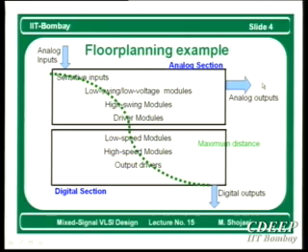And the way I put my pins exactly will be like this. It means that now these digital outputs will go to the pins which are at the bottom. Analog inputs will come from pins which are at the top. And then analog outputs will go to the output pins which are on the right. So this will give at least a preliminary provision or preliminary precaution about interaction between switching noise which is coming from the digital section on the analog section.